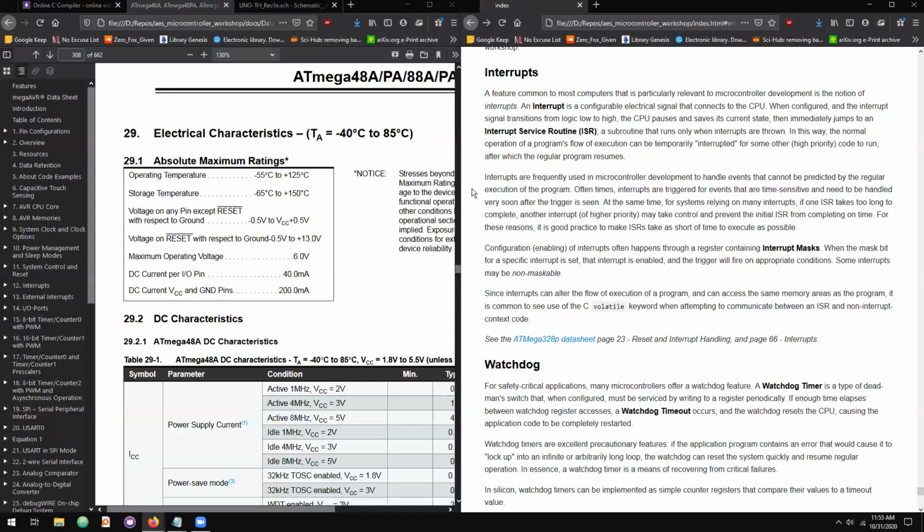So the upside to polling is that you have a very predictable control flow, and you can handle events that are not predictable by polling. That is true, but the downside is that time delay. The upside of interrupts is that you can handle events like that immediately. The downside is it adds code complexity because now you have to jump into a function that isn't part of your regular control flow. And I'll get into why that adds complexity as soon as we get into the project.